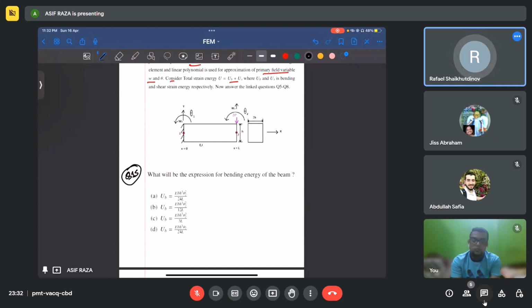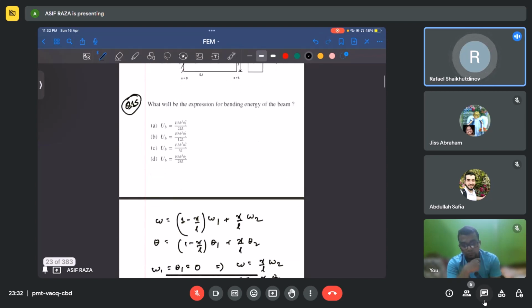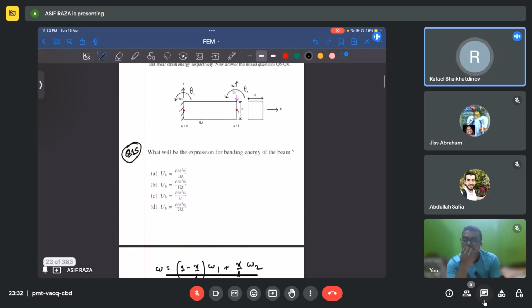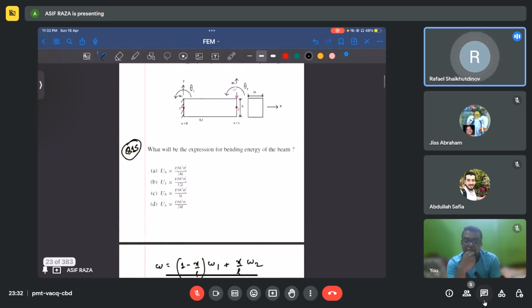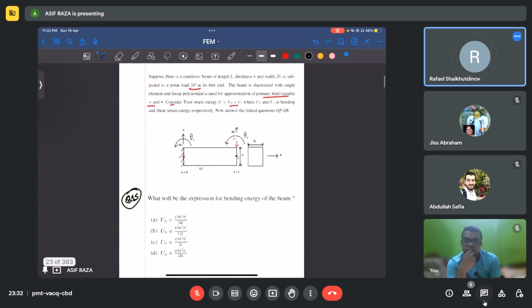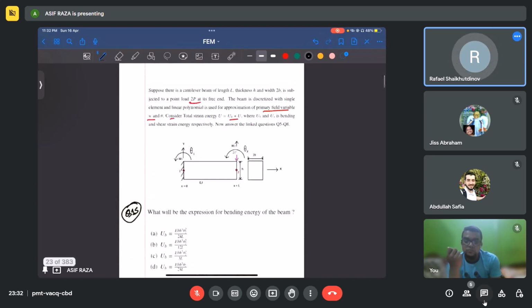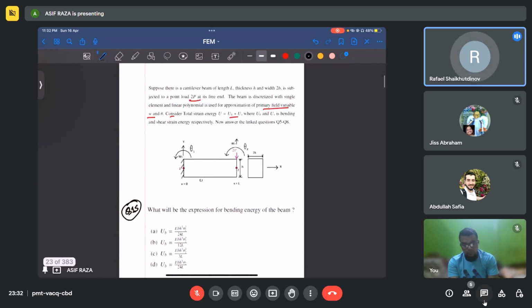The lectures provided the Timoshenko book, and I looked into this book, and there for a cantilever beam, it was said that in the theory of elasticity, we cannot assign the condition theta equal to 0 along the line y at the point where x is equal to 0.